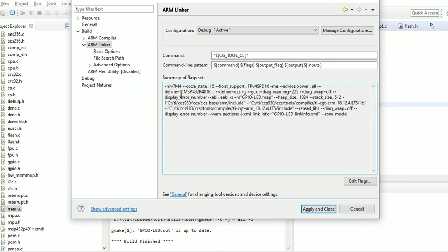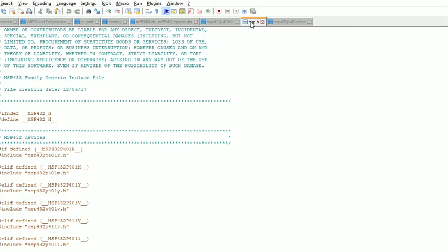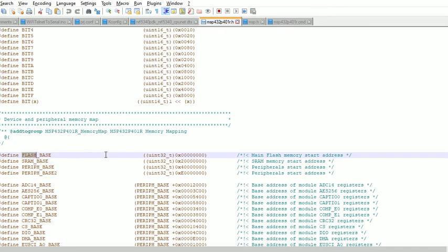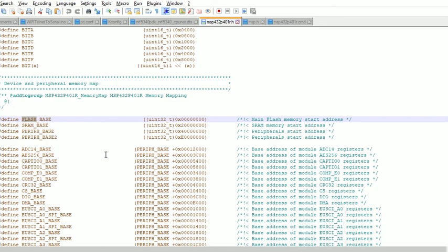If you go back and see the msp.h file, which we generally use as an include in the header files and source files, if MSP432 is defined in that configuration, it includes MSP432P401R.h. That means if you go here, all the registers, everything with the base addresses, will be included in your program.